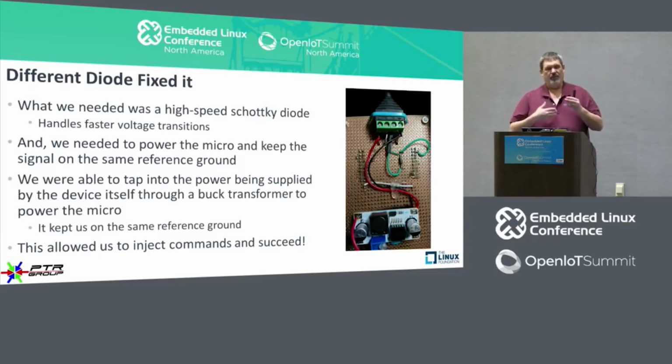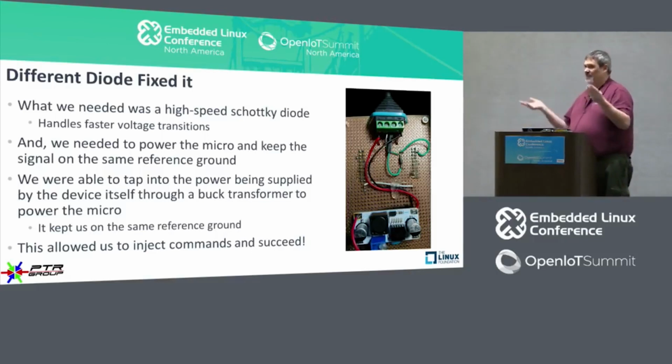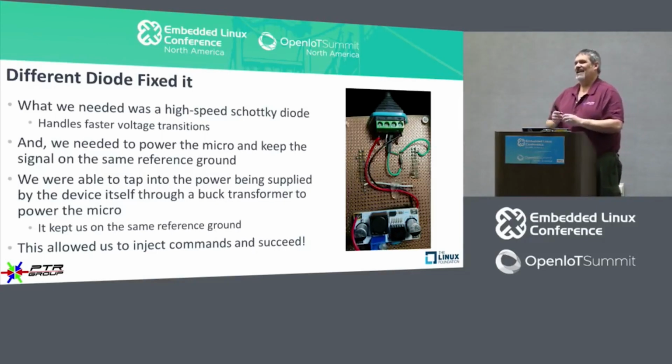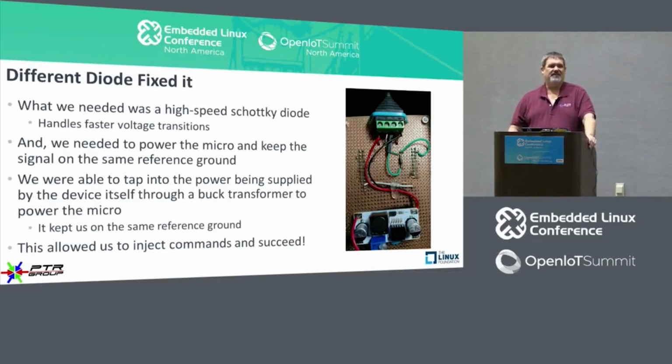And so we said, okay, well, this is probably a 16-bit CRC. And the problem is 16-bit CRCs, there's 24 different 16-bit CRCs. In this particular case, because the 2 people who hold the patent were ham radio operators, we said, AX25, which is a 16-bit CRC that's used in ham radio protocols. Let's try that. Sure enough, that's what it was.